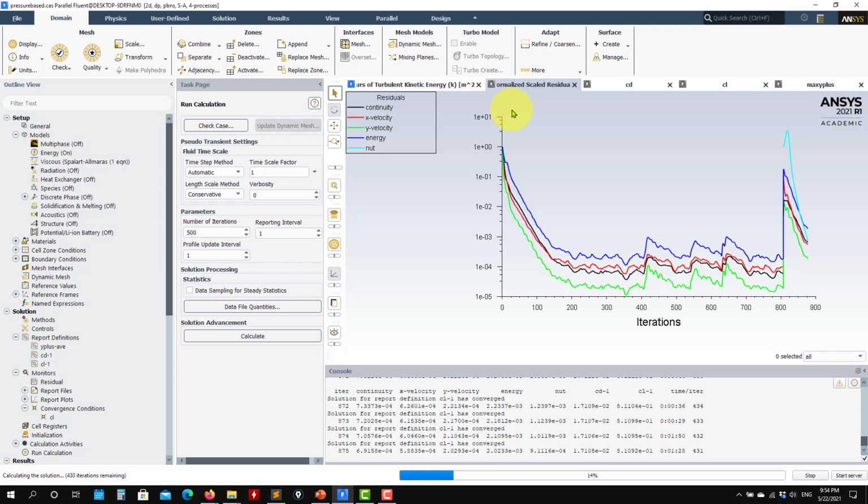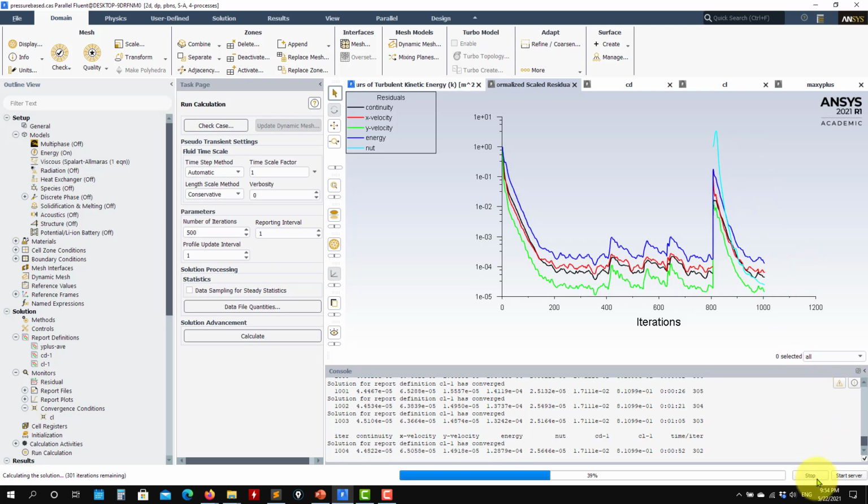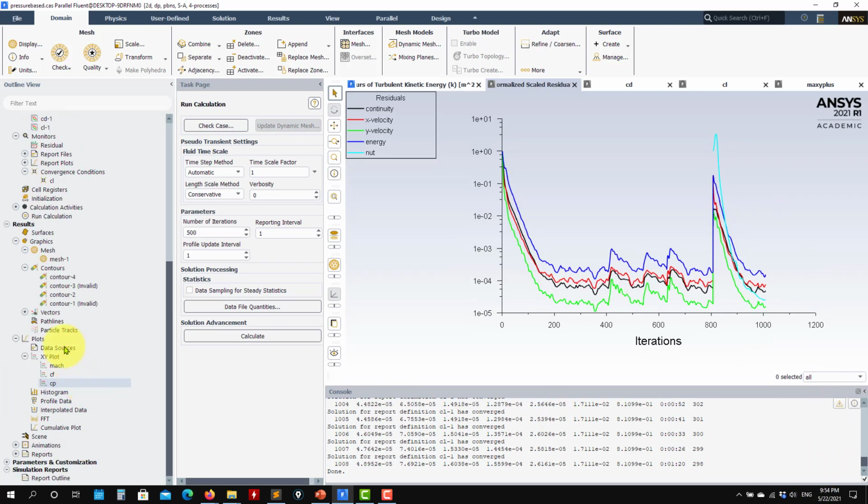But also remember that these limiters, you have them in the linear eddy viscosity models, okay, those models that suffer from this. So for instance, the Reynolds stress model, you don't have that, or nonlinear eddy viscosities, you don't have it because those corrections are already done, because now the viscosities are anisotropic, so there is no need to add this correction. So let's see what happened in this case.